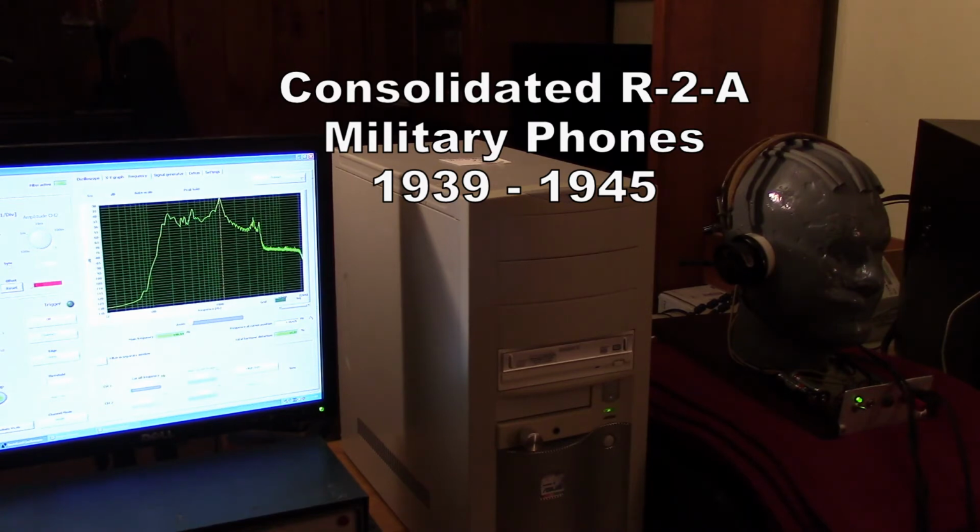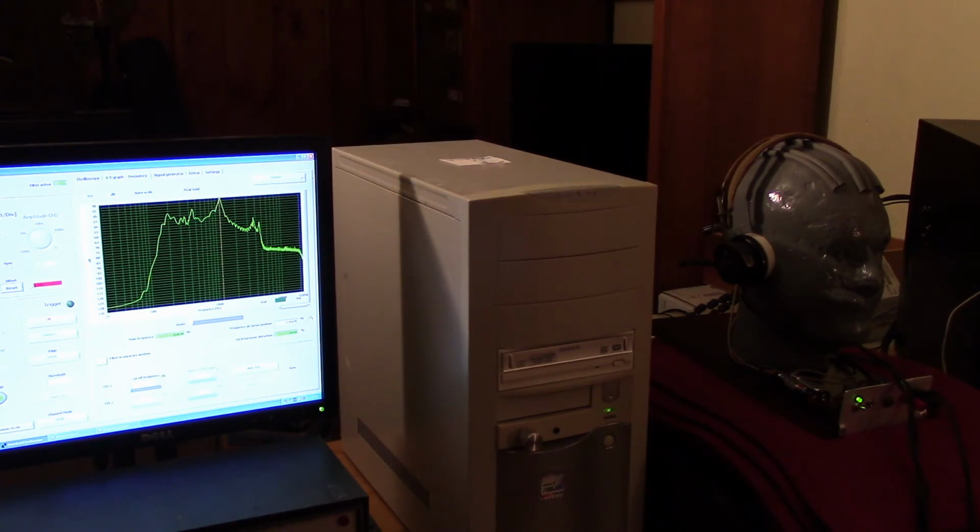You can ignore my voice there, but you can see these are really set up for CW and for voice, and they fall off rapidly above about 2000 hertz, and these are communications quality headsets. I've got a low pass filter in of 200 hertz because we know these really don't work at very low frequencies, so I just filtered that out. Let's reset it again so my voice is not in the passband.